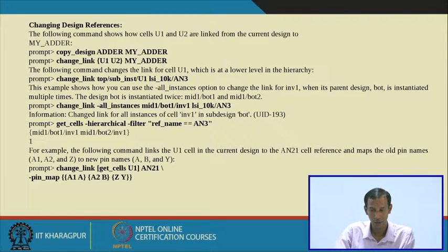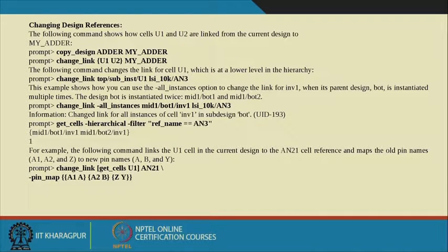In the earlier command, only top/sub_inst/U1 was changed, but here change_link -all_instances indicates that wherever this BOT block is used, it will change the corresponding instance of INV1 everywhere.